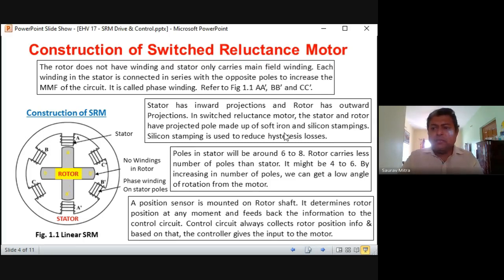Yesterday we saw this in the case of the BLDC motor also. There were three inputs to the DSP control circuit. First, the demand or set point: how much torque is expected, how much torque the driver is demanding. That torque is converted to current first. So that was the set point coming at the input side of the DSP. In this case also the same thing is happening. DSP is digital signal processing.